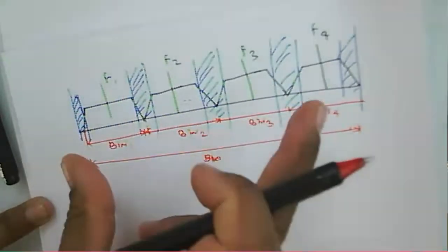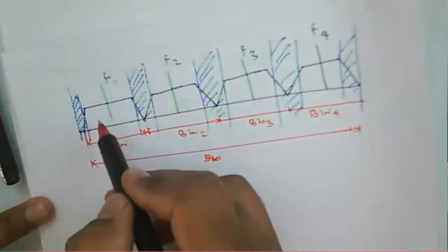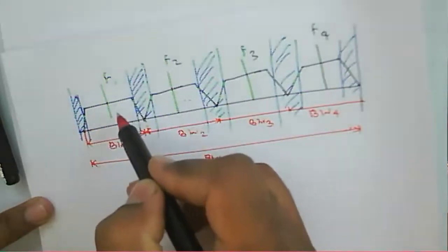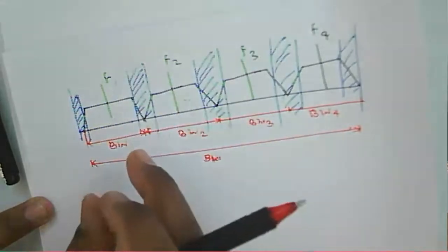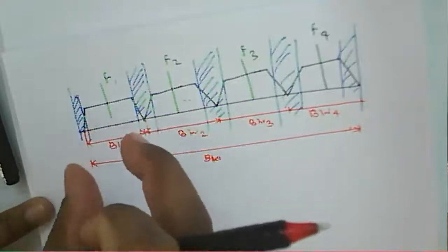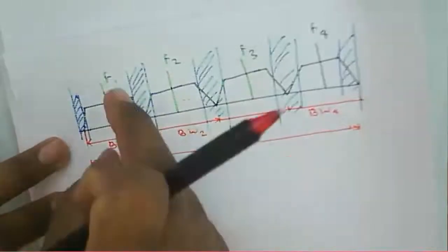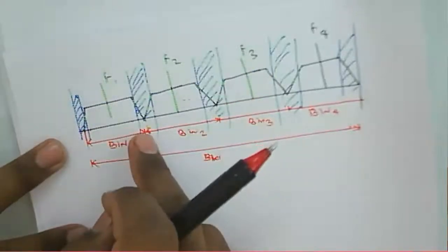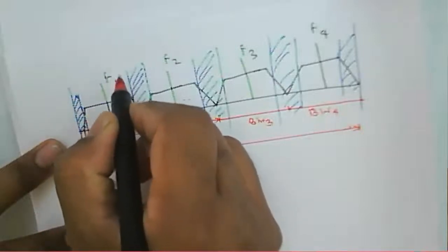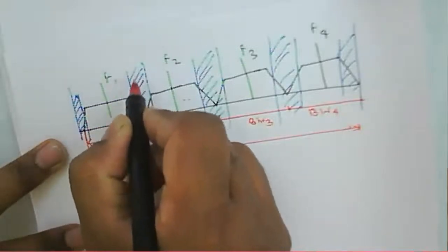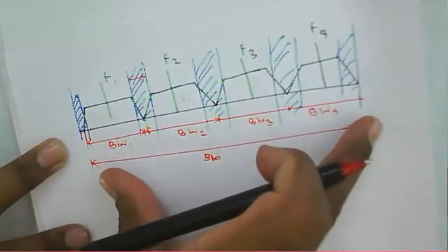It means an inefficient use of the available transponder bandwidth. The guard band is nothing but wastage of spectrum, and because of that wastage of spectrum, it reduces the capacity of an FDMA system.